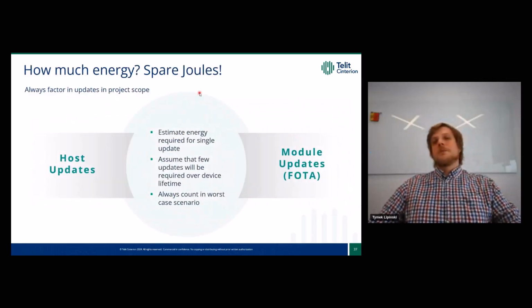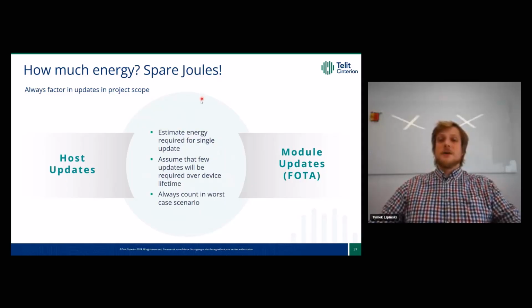We also have to remember to have some spare joules. So we have to factor in the update of our host, so our brains, MCU, SoC, whatever we are using, and we have to consider some spare joules, extra energy, extra capacity in the battery for module updates using, for instance, FOTA, so firmware over the air update. We have to estimate the energy required for a single update for both host and module.